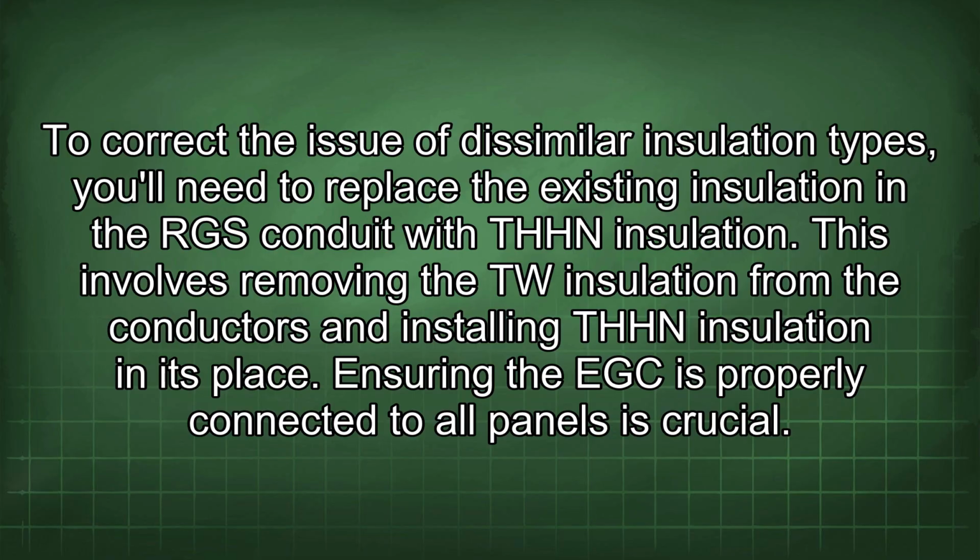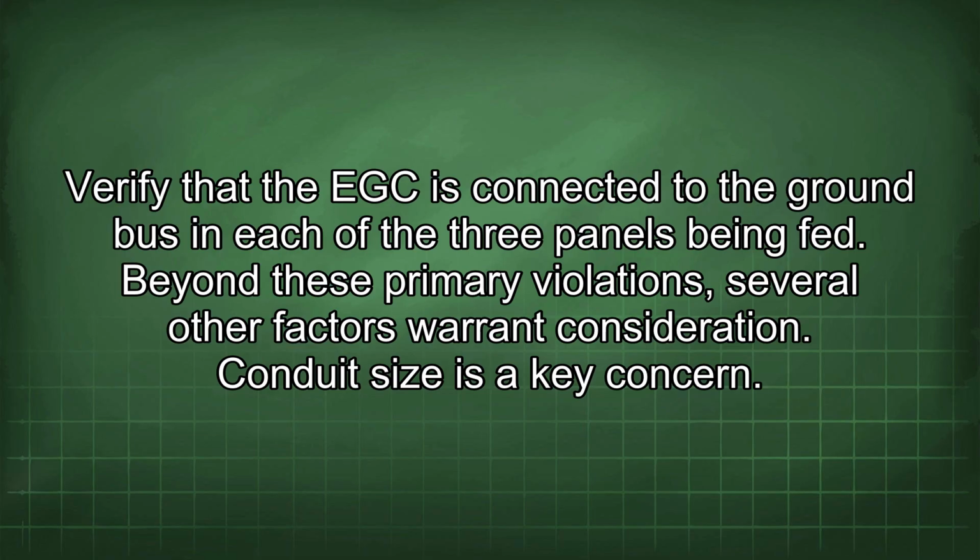Ensuring the EGC is properly connected to all panels is crucial. Verify that the EGC is connected to the ground bus in each of the 3 panels being fed. Beyond these primary violations, several other factors warrant consideration.